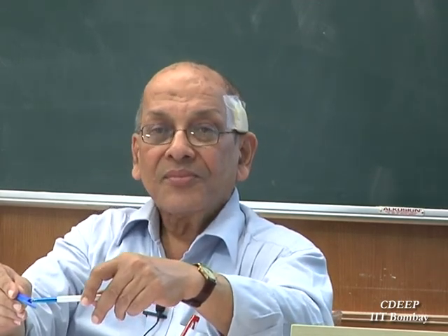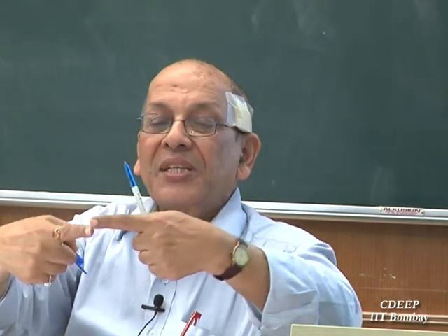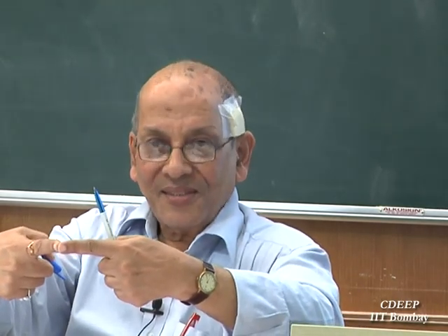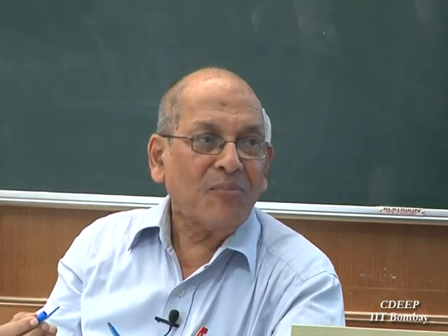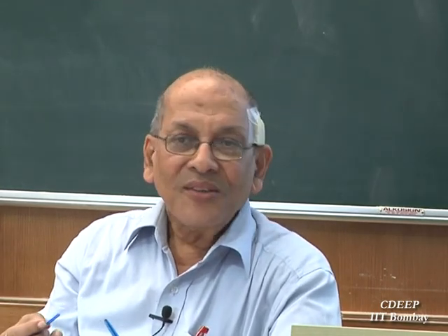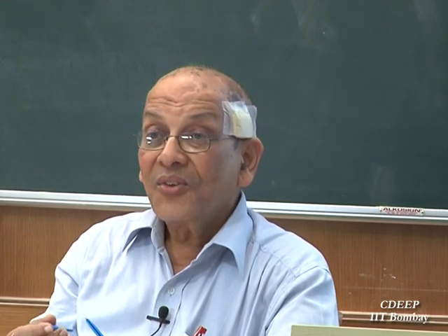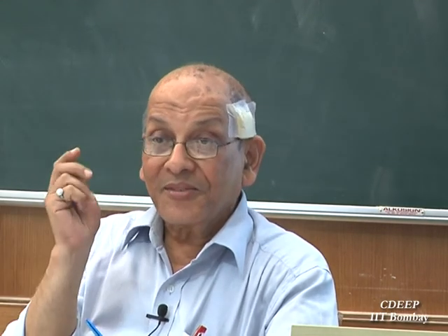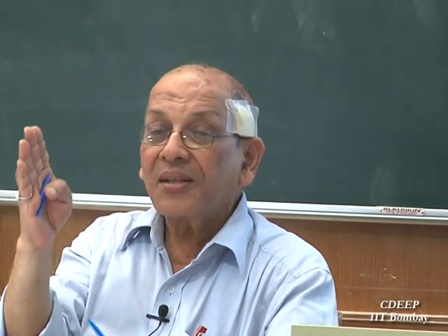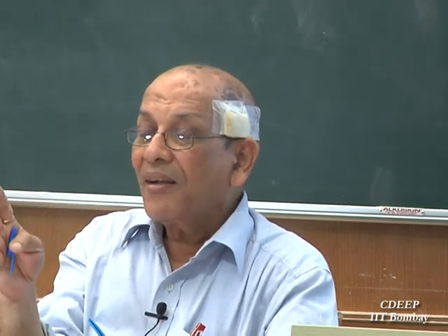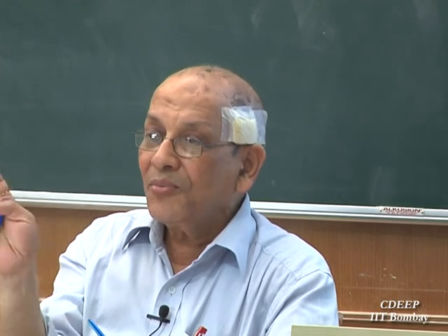There will be two pieces like this, and because the center cross section has become plastic, the entire section is what is called a fully plastic section. The complete capacity of the central cross section has been reached and it cannot be loaded any further.